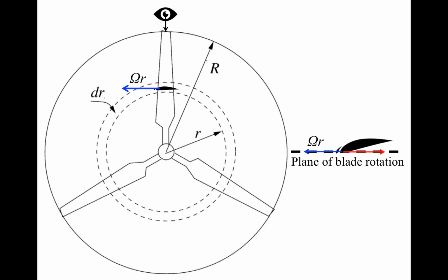If you cannot turn the blade, the stall that the turbine can actually produce is called passive stall, because it's not a stall that's induced actively using the pitch control system. So it's called passive stall. So how is passive stall actually produced?